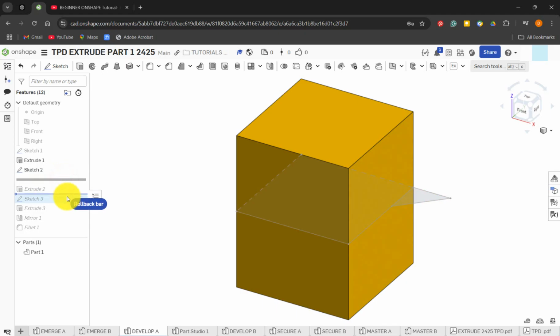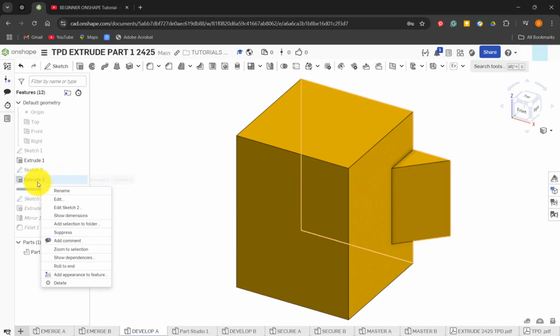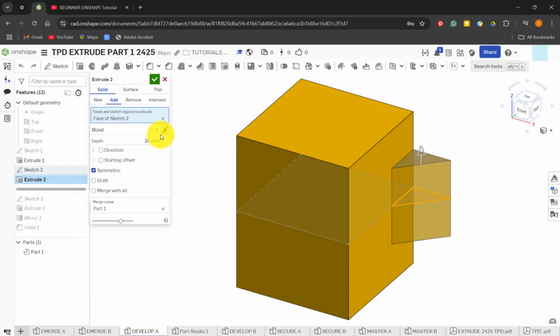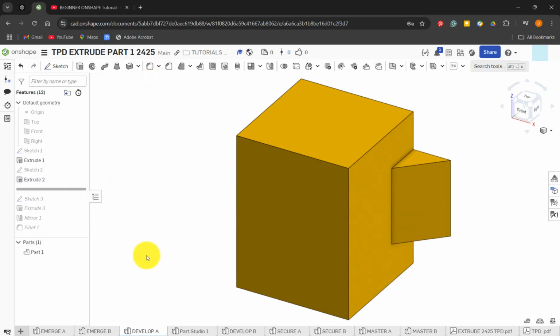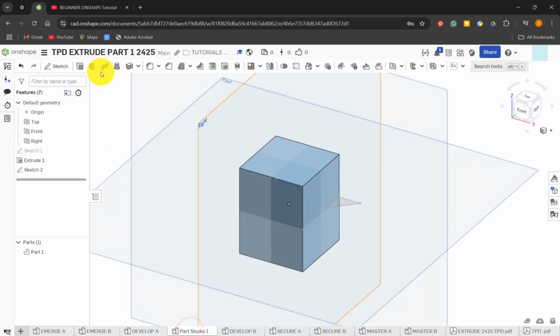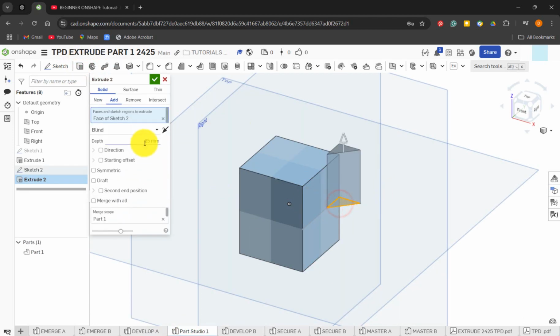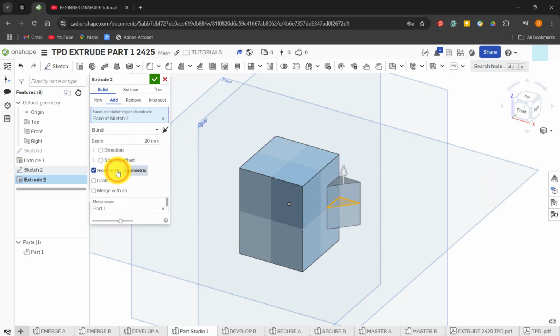So let's go to Extrude. And again, I've extruded this by 20mm symmetrical or symmetric. That's either side, so 20mm. So Shift E or Extrude, select it again, 20mm. To confirm that, you can see it's above, so I want to do it symmetric, and it will split it 10 either side like so, and confirm it.